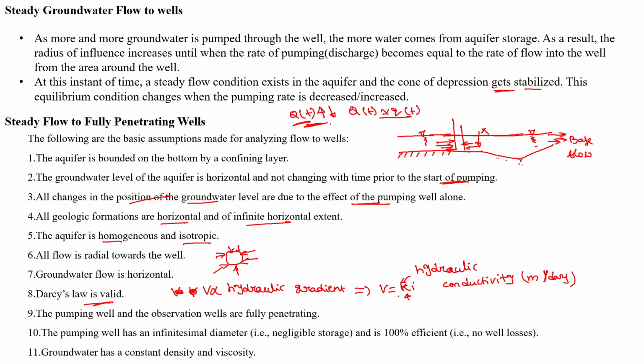So we use some kind of well testing or different methods to estimate this K. We will solve a similar example where our interest is to calculate the hydraulic conductivity using other given data. The pumping well and observation well are fully penetrating. Practically we won't have the hydraulic conductivity value, so to estimate it we use the pumping well as well as observation wells, and continuously monitor the drawdown. By using those relations, we calculate K and T, the transmissivity, and other values.